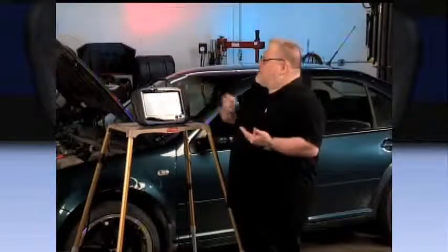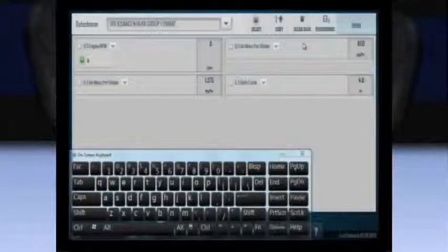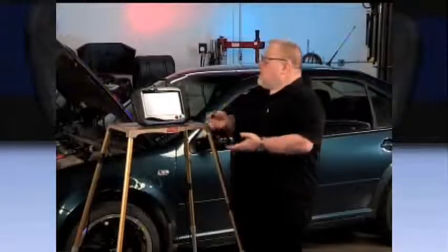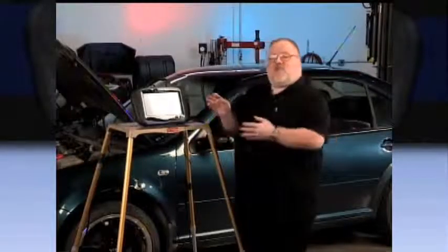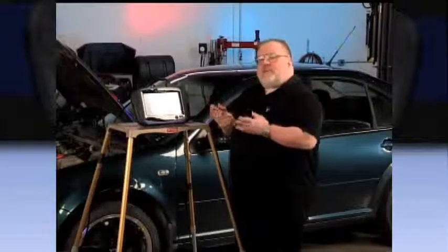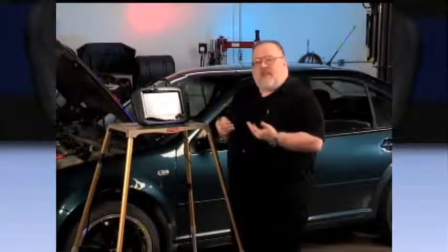What we would expect to see on this particular vehicle, normal idle, if everything is working the way that it should, is approximately 240 to 340 milligrams per stroke. And what we're actually measuring here is EGR, not actual airflow. It's a measure of EGR function, but this gives us a good idea of what's happening inside of that engine.